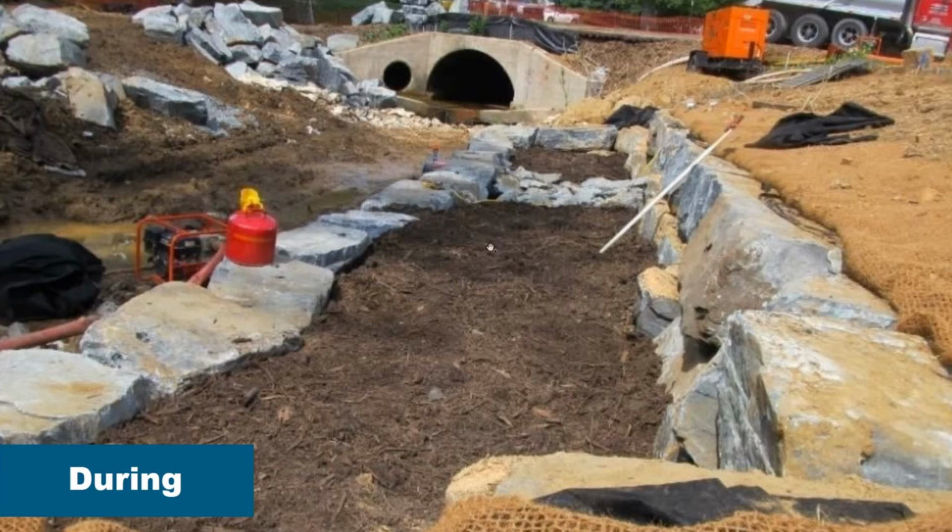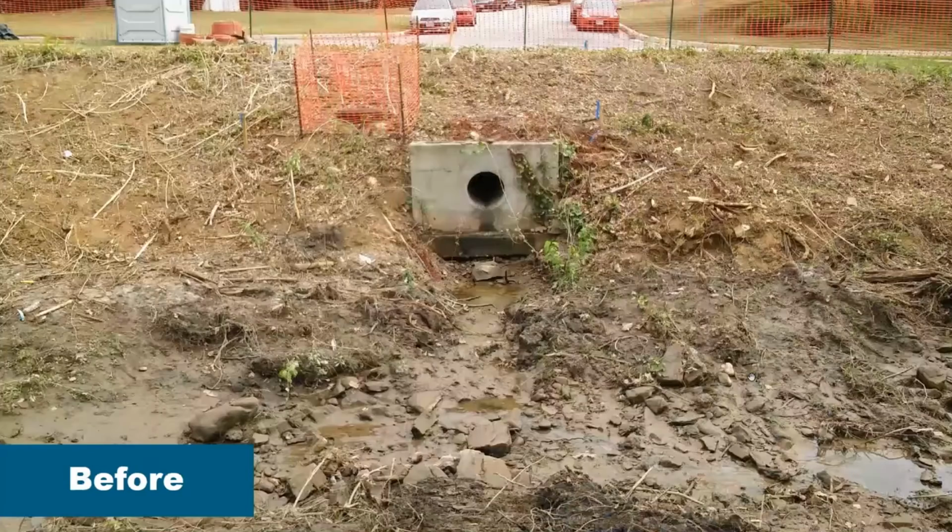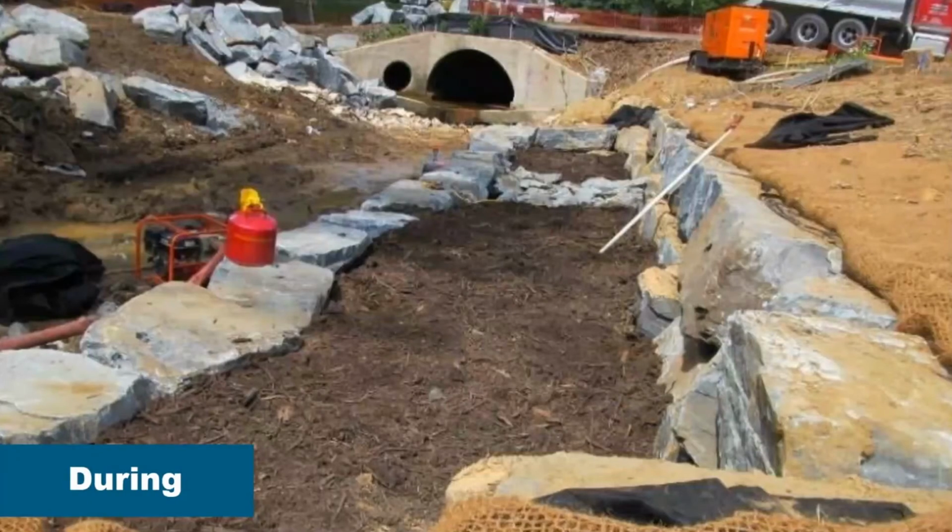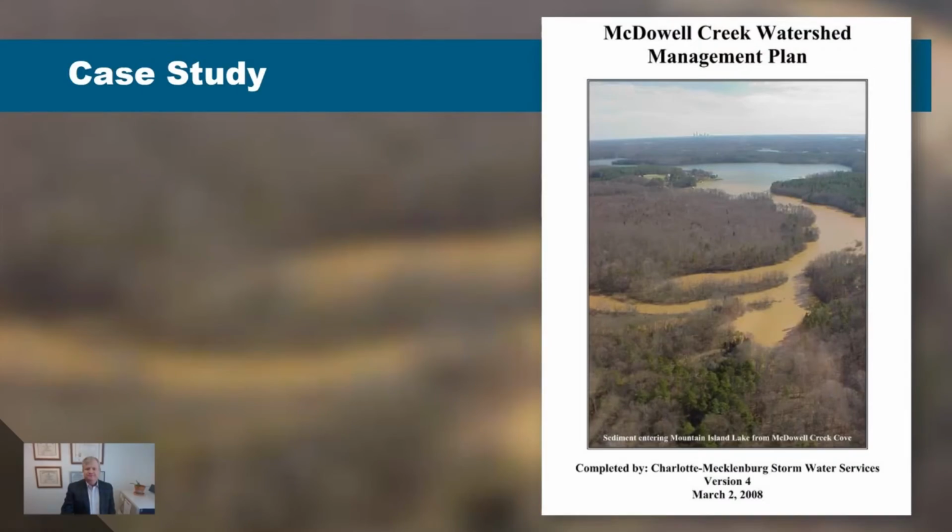And you see the mulch and other things that come in just like a rain garden, but a rain garden that's not going to be maintained. It's just going to kind of self-naturalize and become part of the system. And then also this larger stormwater outfall can access it during flood events. So this thing has treatment for that little pipe you saw in the before picture and treatment for the larger channel that it's part of.